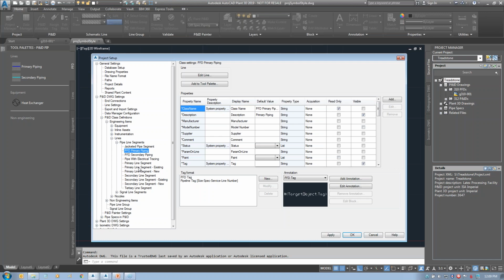That way I would be able to differentiate very easily that these were different lines than my normal pipes. Now the ideal situation, and this is what that ideal was on the ideal page, would be for them to separate process flow diagrams from P&IDs completely. But since they can't right now, this method here allows me to keep, by just putting PFD before everything, I can recognize that's for a PFD, don't use it when I'm working on a regular P&ID.